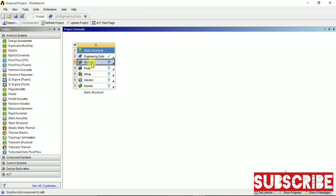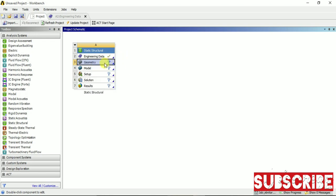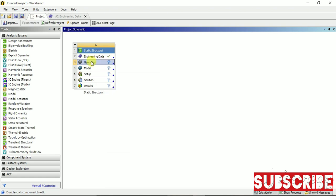Now in this version 19.1 there is a feature called Geometry. In Geometry you can make geometry in two types of software. First is SpaceClaim, and the second is DesignModeler. Since in the previous versions only DesignModeler is present, I am comfortable with DesignModeler. You just have to right click and click on DesignModeler. It will open a new window that will contain the toolbox to make the geometry.